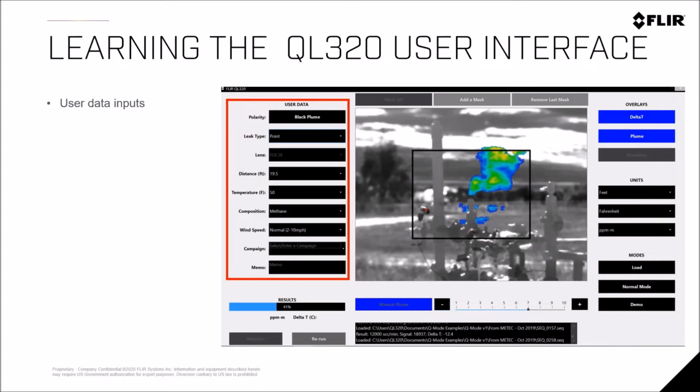But even more important is the accuracy of the temperature. That temperature is the ambient air condition around where the leak is. In other words, if you have an anemometer, you would want to know the air condition. If you're standing indoors in an air-conditioned doorway but looking outdoors, it's not where you're standing, it's where the leaking component is. It is not the temperature of the component. If you have a warm valve, it's not the temperature of the valve. It's the temperature of the air near where that valve is.